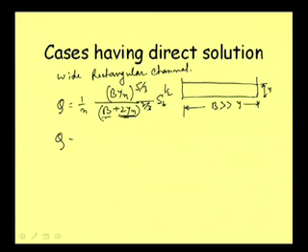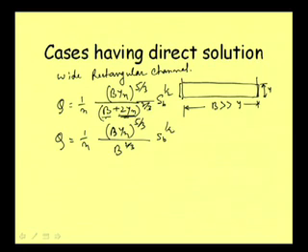So, we can write Q is equal to 1 by n, then (B yn) to the power 5 by 3, and this we can write as B. That means, this small length we can neglect, and we can write B to the power 2 by 3 and S to the power half. Now, you can see that yn can be separated out.